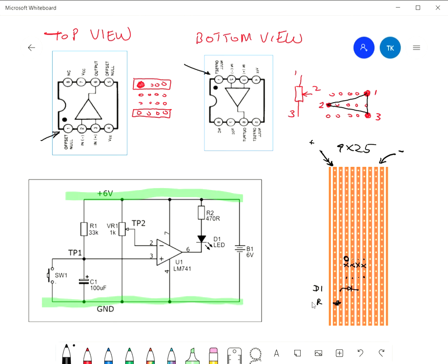So that is R2. The way that we do it is we've connected our LED, remember the polarity, be careful of that, to there. The copper strip connects it to R2, which goes all the way to the positive rail. And we just want to make sure that this strip of copper is not connected to anything, so that we don't clash with any other connections. There isn't right now, so we're good.